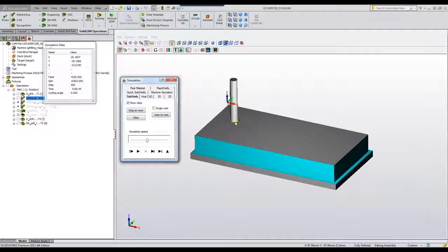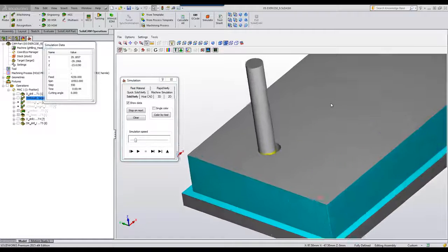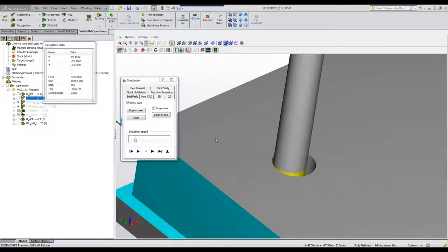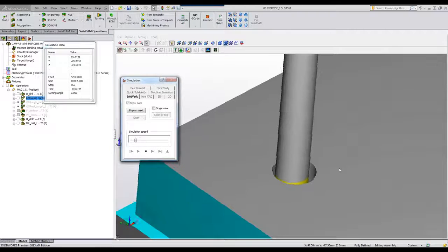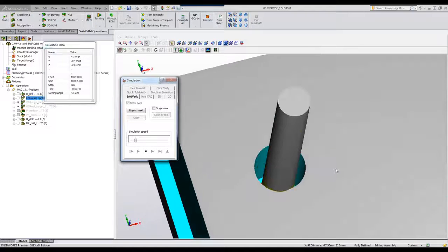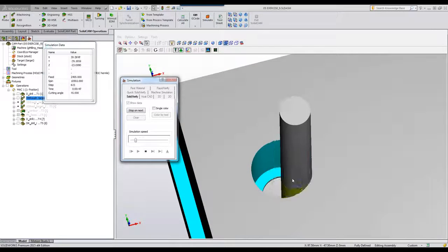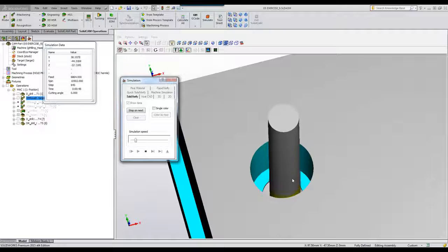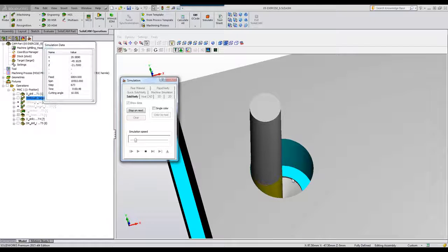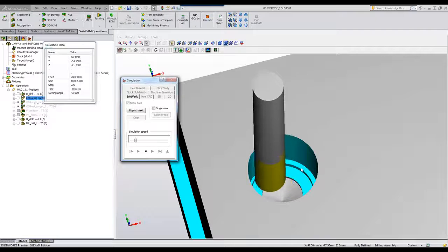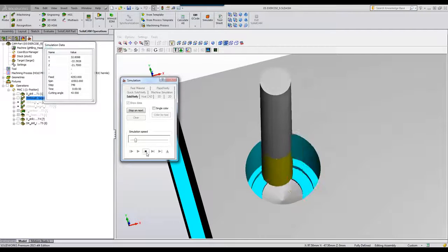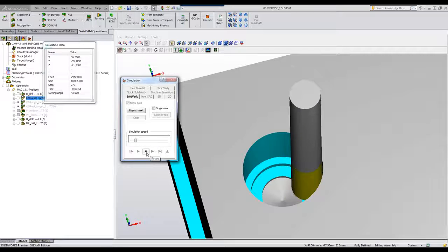It sees what's there. Now let's continue on down, and I'll continue a little slow over here, because I want to also zoom in to this area itself. And I'll do that by coming in as close as I possibly can over here. And let's see what happens now. Right now, it's actually machining that bottom step over there. And it's doing that in a spiral form. And now it's going up to its next step. This is the optimized step up that I talked about.